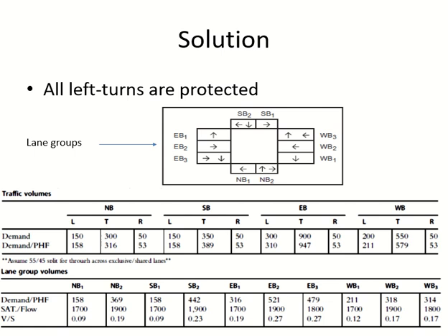Then we have to identify the lane groups, the lanes which have the same movement. Here none of the lanes had the same movement, so we had to divide them one by one. Then we converted the demand into demand flow rate, dividing by peak hour factor. One step which we didn't have to do was convert it to passenger cars, but otherwise you would have to divide it by the heavy vehicle adjustment factor as well.